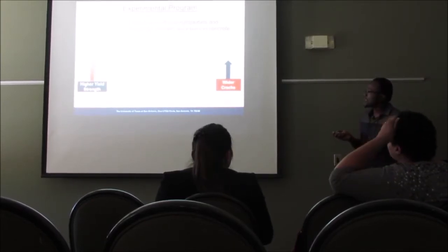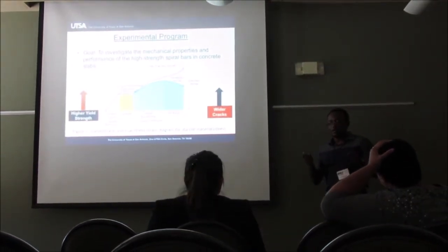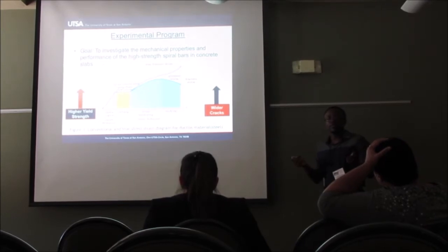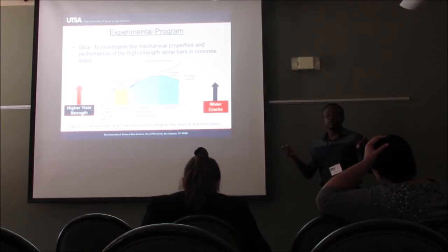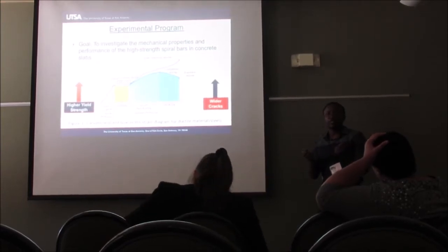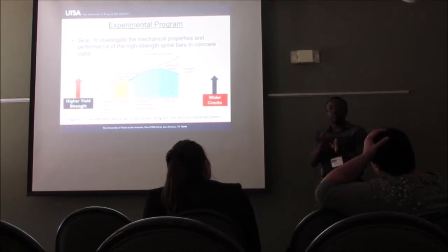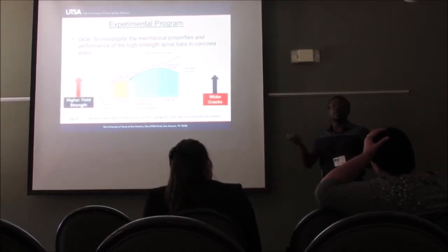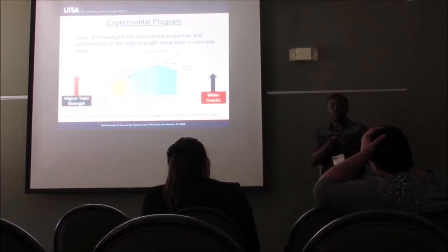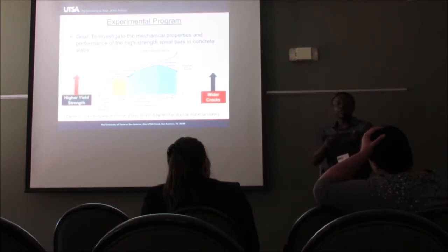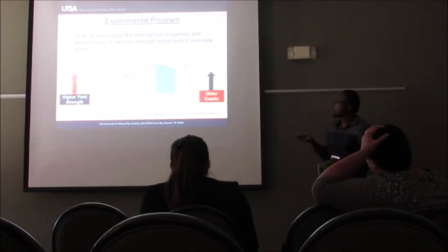Yeah, so elastic behavior means that if I have a steel bar and I pull on it, before I create any permanent deformation, my bar is still elastic. If I pull on it and let go, the bar is able to recover all of its energy. And plastic behavior just means that any more pull past the yield point creates a permanent deformation. Think of a piece of plastic: you pull on it, and at some point whatever you keep pulling just increases that deformation. That's the type of behavior that we observe.